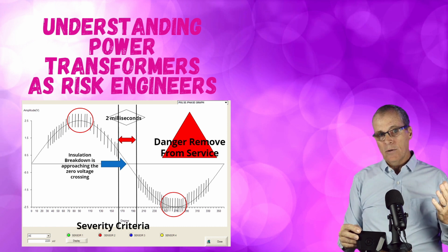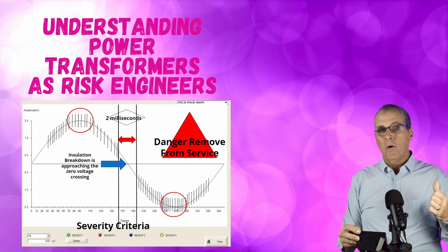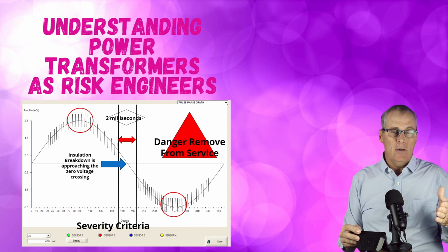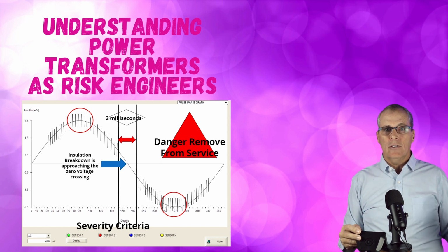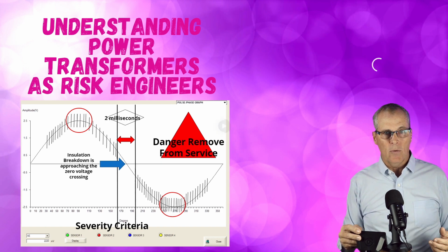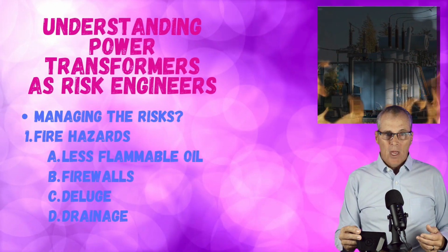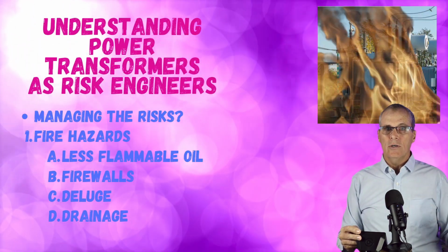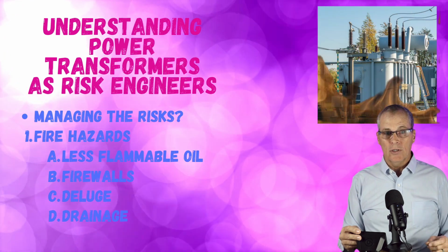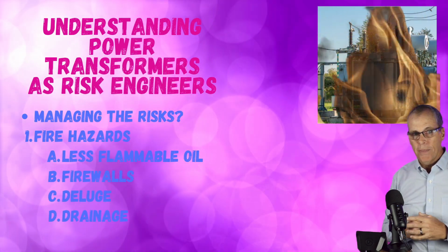Okay, so that's the beauty of partial discharge, is that you get this number and you decide what to do with it here and today. You don't have to wait and wonder, what should I do? And you don't have to ask yourself the question, why did my transformer fail when I had good DGA? I'll talk to you about a plant that had good DGA, no moisture, and it failed, and partial discharge could have helped us prevent that.